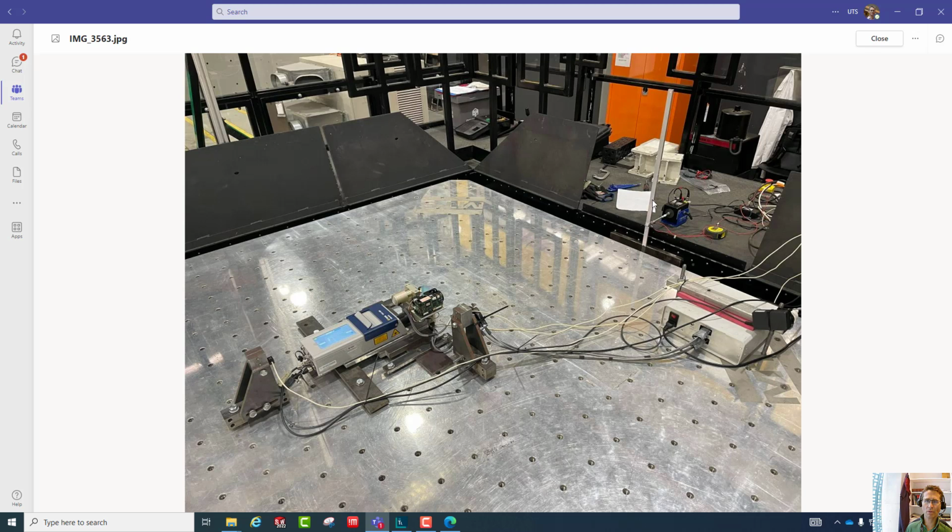Run 2 was at point number 2. Run 3 at point number 3, 4, 5, 6. The positions of the points on the beam are noted on the back side of the beam. We moved the laser beam using the scanning unit and the bespoke scanning head, just adjusting the voltage to one of the galvanometer mirrors to reposition the laser beam along the length of the beam at these 6 different points.